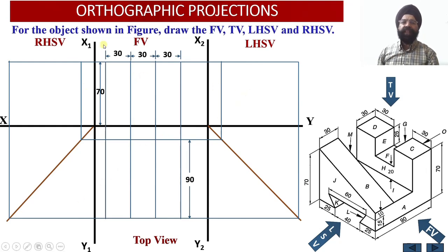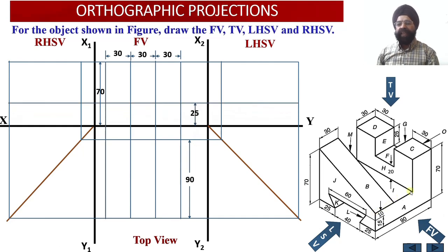Now let us start with the front view. Once we are looking at the solid from the front, we are able to evaluate that these are the projections that we are going to get. So this is the height from the front, this is the lower web, right? Corresponding to the lower web, the height of the lower web is equal to 25 millimeter. So I have drawn a projection line over here at a height of 25 millimeter from the base of the solid, right?